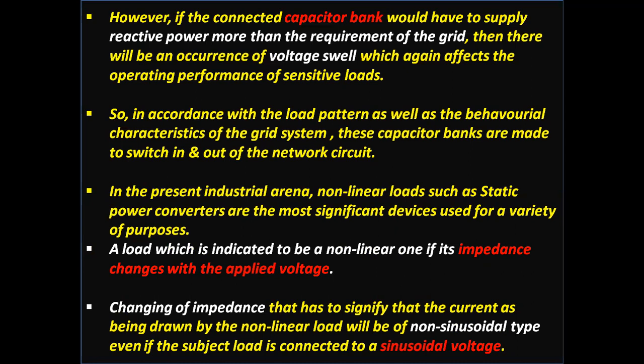Changing of impedance signifies that the current drawn by the nonlinear load will be non-sinusoidal, even if the load is connected to a sinusoidal voltage.